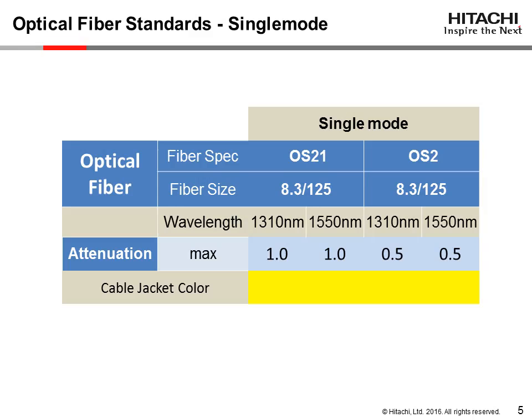Single-mode OS1 and OS2 have no bandwidth requirements, as single-mode has virtually unlimited bandwidth. The information carrying capacity is only limited by the light source and the attenuation over distance. Note that single-mode fibers are designed to operate at longer wavelengths, 1310 nanometers and 1550 nanometers, than multimode and carry a light signal over long distances. And at these wavelengths, single-mode fiber is very effective and provides very low attenuation properties.